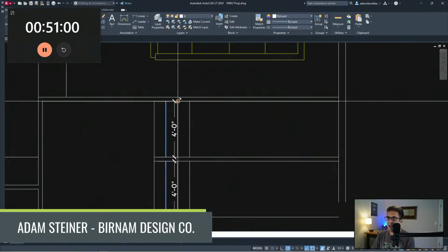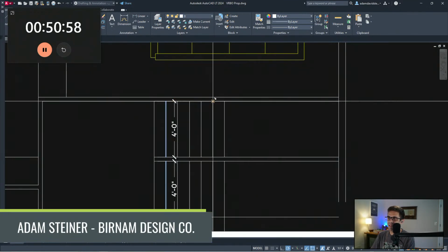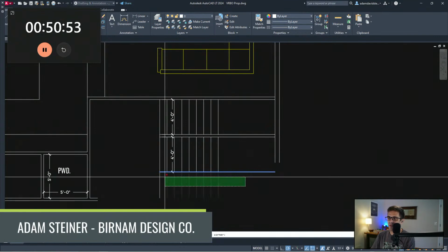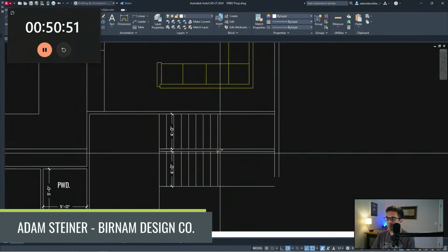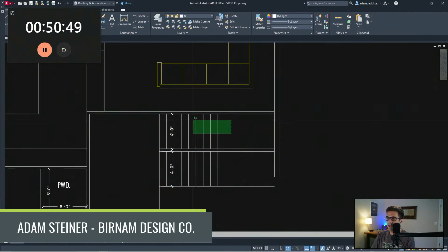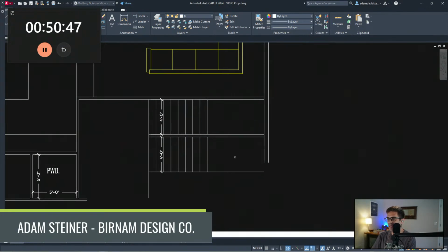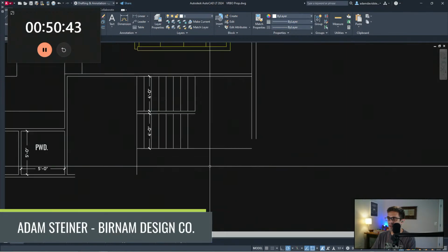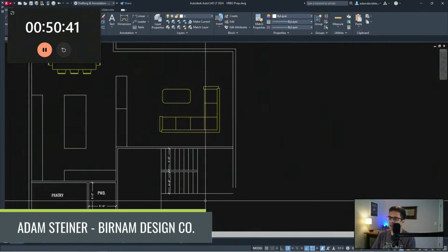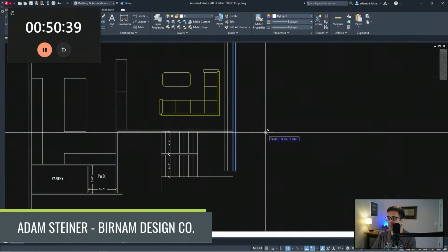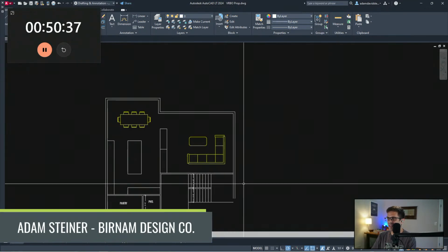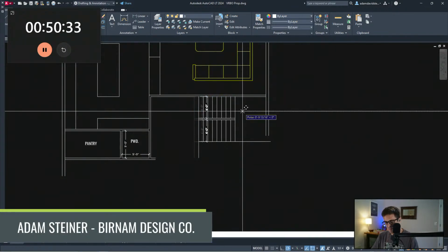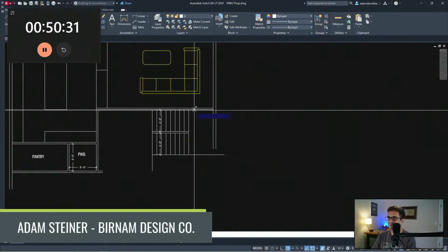I usually show 10.5 inches for treads. You only need 10 by code and you're fine. But 10.5 gives you a little bit of wiggle room on framing. And then I'm showing 18 there, because that gives us room for 10-foot main floor ceilings, which is fun. I feel cheesy saying this to clients, but I've said to a lot of clients, like it kind of feels like 10 is the new 9 foot. So, seeing a lot of those.